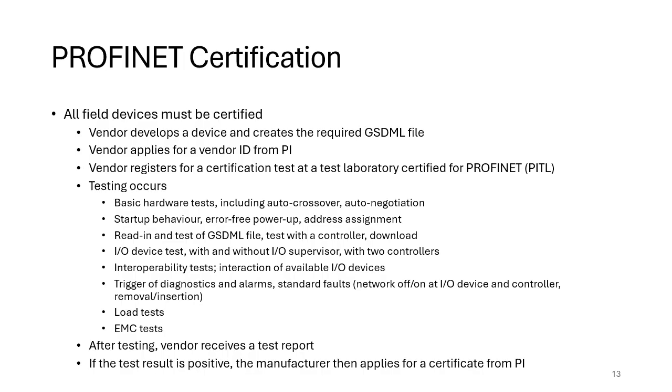There would be I/O device tests with and without an I/O supervisor, possibly with two controllers as well, to make sure that the application relationship arrangement works. There would be interoperability tests and interaction with different available I/O devices. There might also be testing of diagnostics and alarms and standardized faults, such as network off or on or device removal and insertion. There might also be load tests and EMC tests.